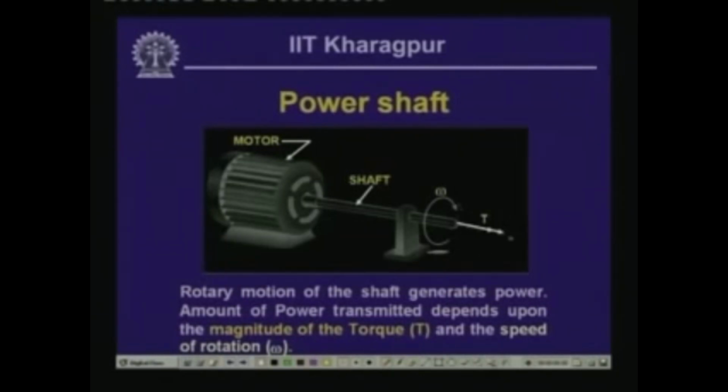So, it undergoes rotation at a rotational speed omega, and it transfers a twisting moment T. The twisting moment transferred to the other device is exactly in the same direction as this angular rotation. That device gives a resistive twisting moment in the positive direction, and that is what is shown over here. This particular direction is the positive twisting moment acting in the transmitted shaft. As a resisting moment it acts in the positive direction, and this is what is demonstrated here.